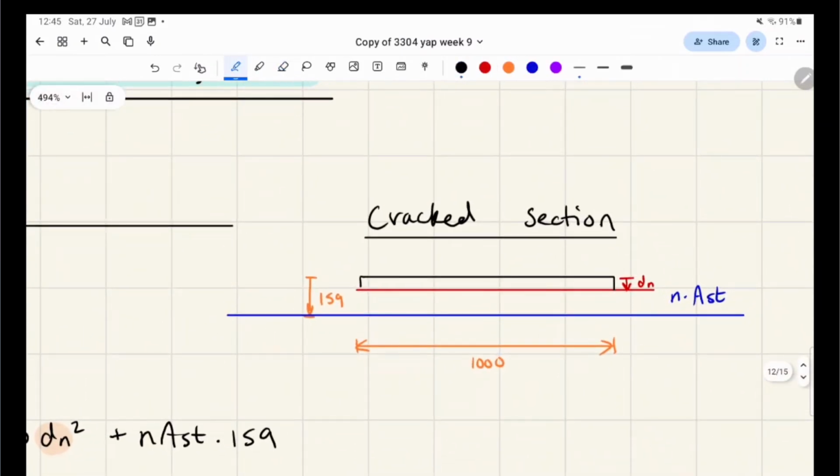What makes the second stage of concrete, or the cracked stage, unique? What are its key features? Basically we say that the concrete on the tensile side is useless, so we disregard its area. If you remember before, our depth to neutral axis used to be about here, and our concrete was still alive to here. But as soon as it cracked, it jumped up a lot.